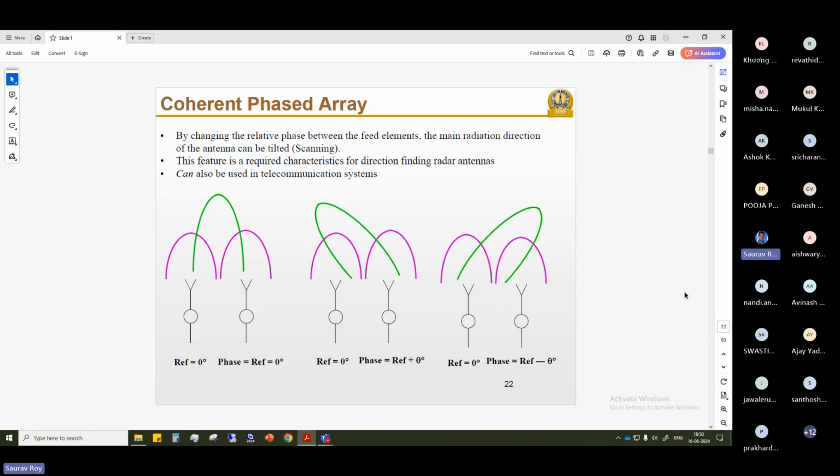And accordingly, if you have to cater to moving or autonomous vehicles, drones and all this, you can track and move your beam towards that direction, so you will minimize the loss of the signal. Because of the gain in a particular direction from the phased array, the SNR will be high in that direction. That is how we overcome path loss at higher frequencies. We need more and more sharp pointed beams so that we don't lose signal here and there.